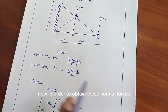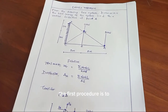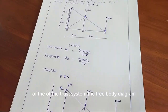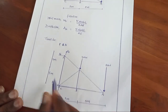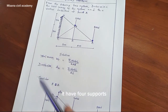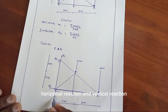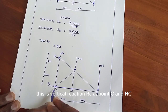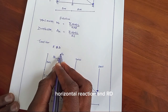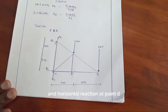Now, in order to obtain these normal forces, the first procedure is to draw the free body diagram of the truss system. This system, this cantilever support, has 4 reactions: horizontal reaction and vertical reaction. This is the vertical reaction at point C, VC, and HC, the horizontal reaction. And VD, the vertical reaction at point D, and the horizontal reaction at point D.